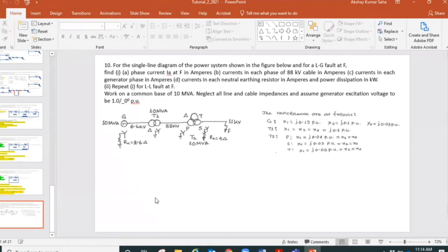The other thing, we must make sure that the secondary voltage where the transformer is connected on the common side, or if the common is on the primary side, then we have to make sure that the voltages are the same on whichever side we are connecting them in parallel. We can connect them in parallel on the secondary side. We can also connect them on the primary side. We can connect them on both sides. That's possible. So we need to make sure that the voltages are the same if it's single phase.